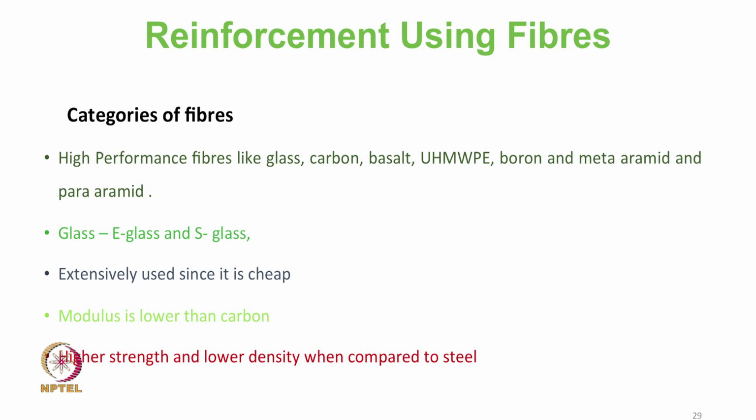There are different types of glass fiber. The E glass, which is strong and relatively lower cost, but its modulus is low, less than other fiber, typically 500,000 psi. S glass is stiffer than E glass and its tensile strength is one of the highest of all fiber materials.